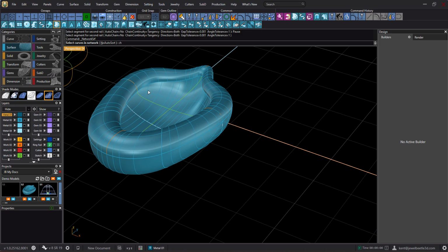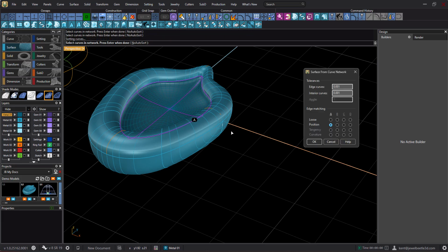But you can type the word chain in the middle of a command. So not chain edges, but just chain. If I hit enter, check it out. Select the curve in the chain. So I click here, and it chained it. It went all the way around. And so that's it. You hit enter, and now you're on to the next curves. So chain made one selection. And then I can do this, and now I can run that command, whereas I could not have before.